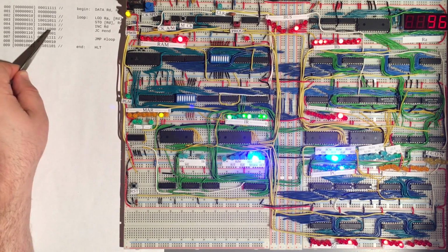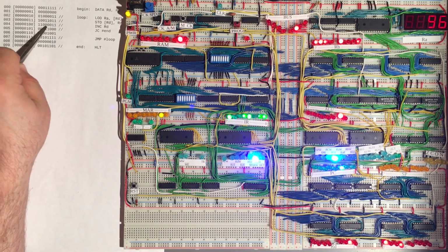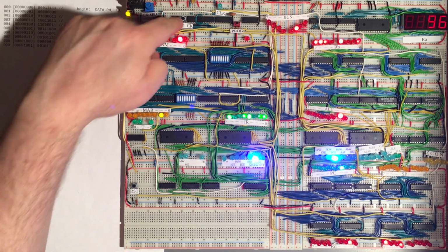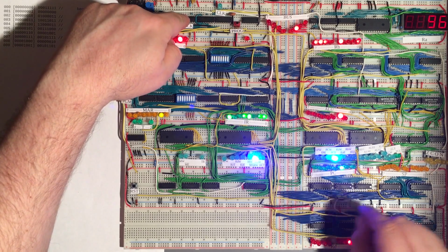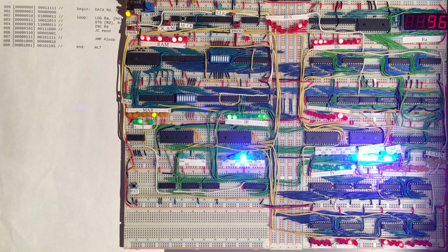And the next instruction in our program is this increase instruction, which is an ALU instruction. So we're at address 4 right now, and so we're at this increase instruction. So again, time t0 and time t1 are always the same. We need to get that address into the memory address register and then get the opcode into the instruction register, and so there it is.